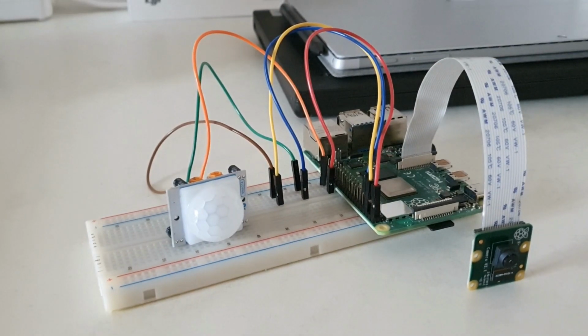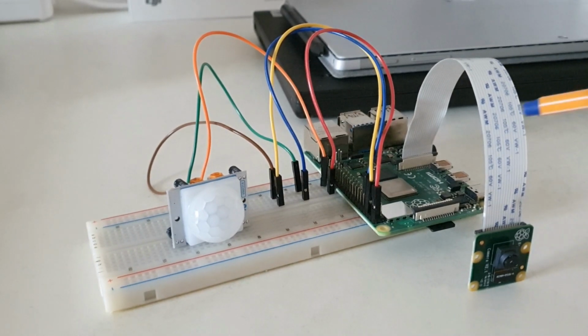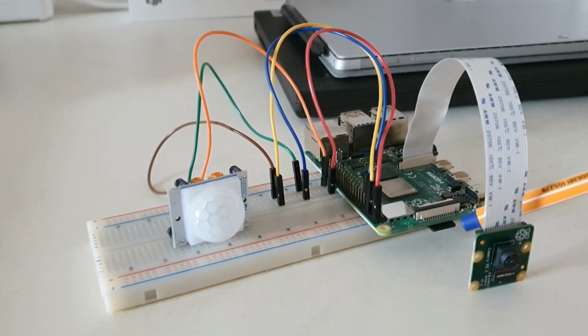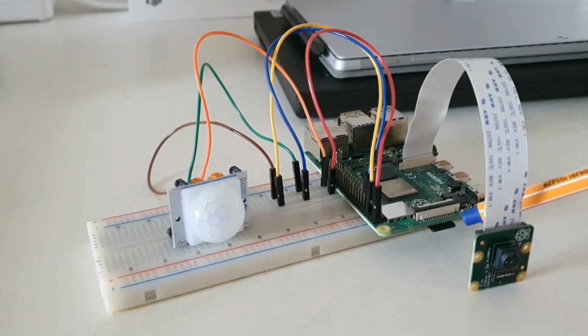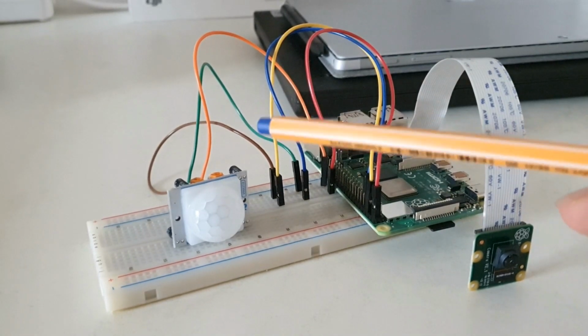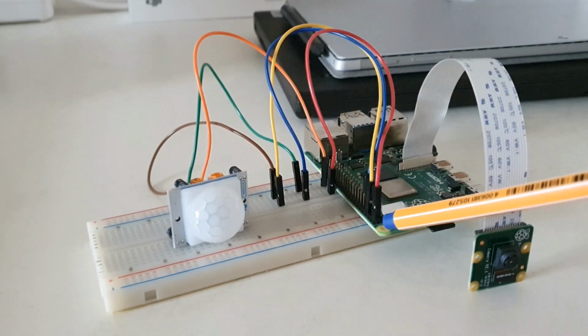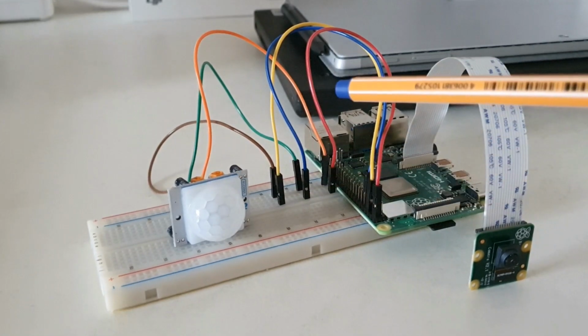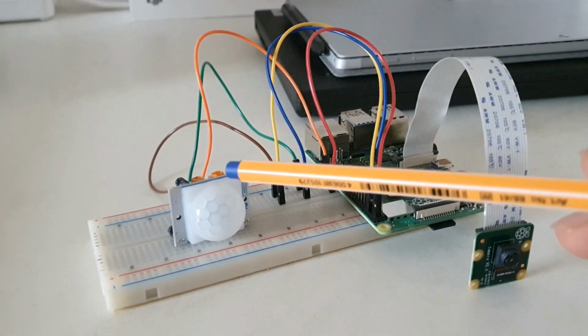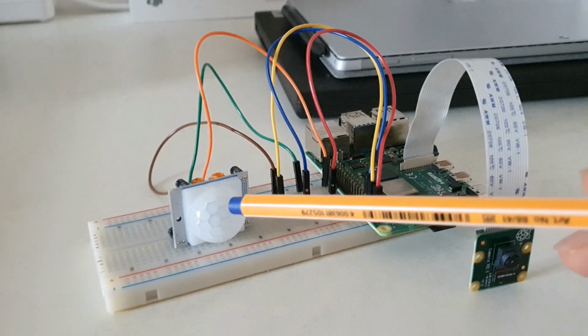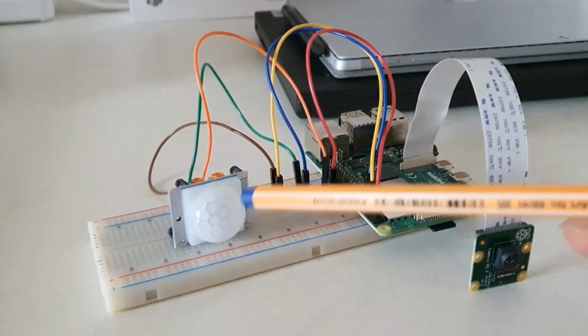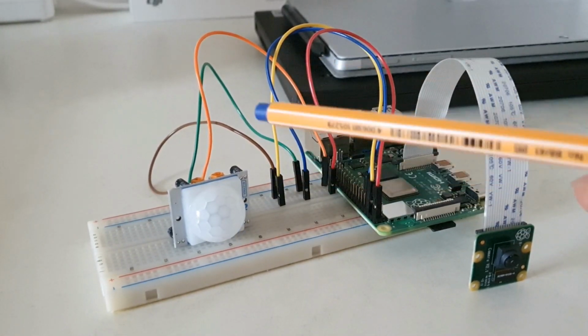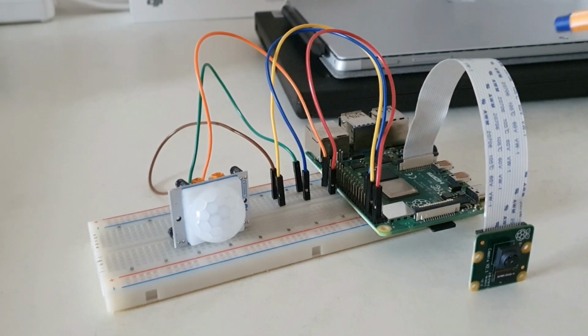This is the final hardware setup where the camera is connected with the Raspberry Pi. The micro SD card is prepared with the latest Raspbian image and it is also inserted into the Raspberry Pi. The PIR motion sensor is also connected to the Raspberry Pi via GPIO pins. The Raspberry Pi will provide power to the PIR motion sensor, which detects motion in a 120-degree angle. So the best place for setting up these devices is the corner of the room. Now let's power the Raspberry Pi and go for the programming.